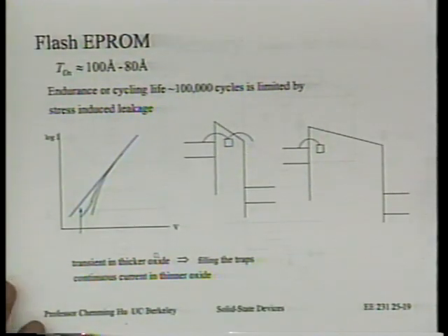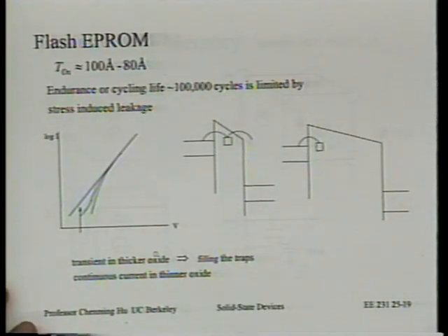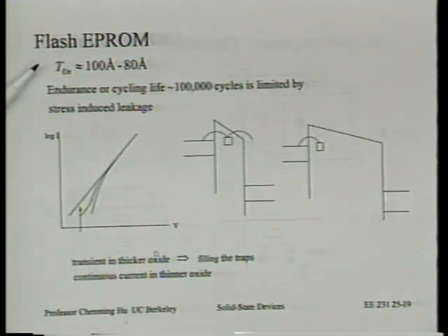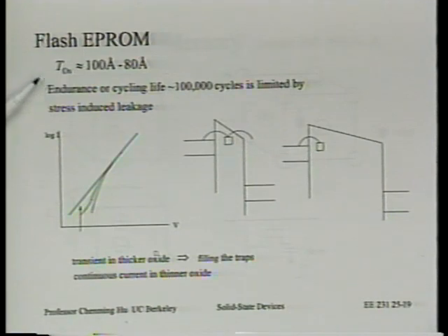So today, when we talk about non-volatile memory, mostly we talk about some kind of flash. And by the way, I maybe should mention, besides flash, what else is there? Well, there's the UV EEPROM, for example. We can erase them by UV light. Now, certainly flash today is the important type of non-volatile memory. So for flash memory, this gate oxide or tunnel oxide is about 100 angstrom, maybe as thin as 80 angstrom, but really couldn't do that.